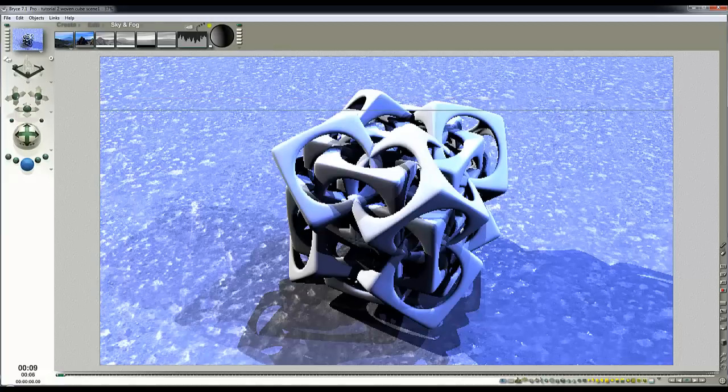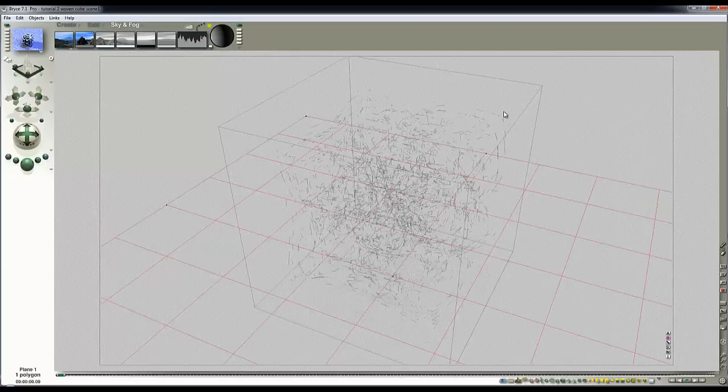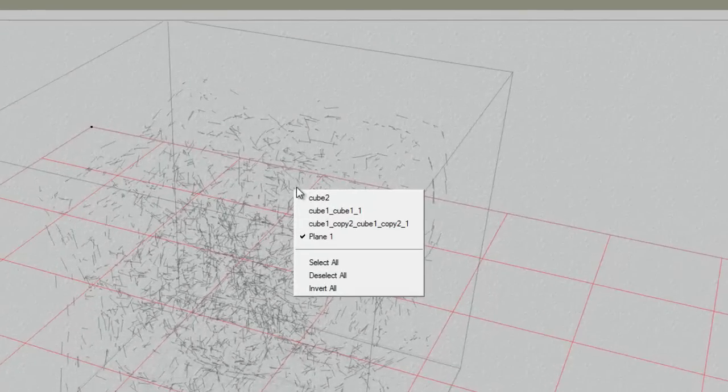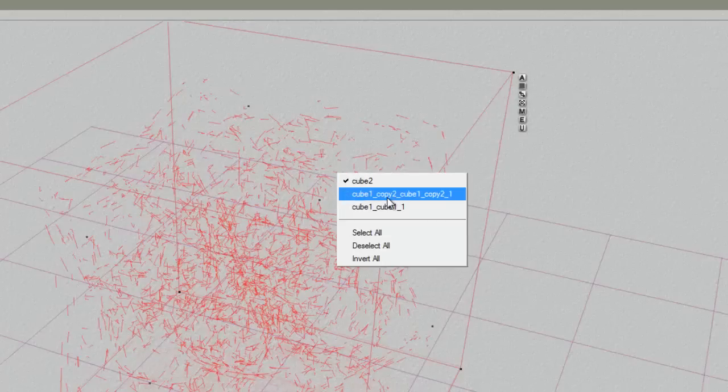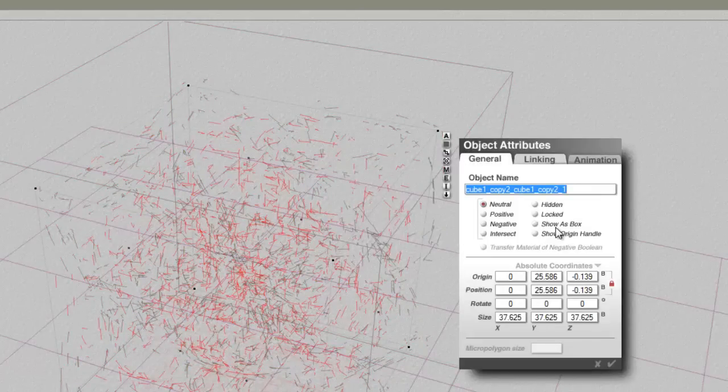So on these then we'll want just two different metals to show the difference between the two models. If I hold the control key down and left click where the cube is, you can see there's the entire cube model, which is the group here, and then right click again, there's the two components. To make life easier for yourself, it's a good idea to select the components. So that could be, and change the name, inner group, inner selection. It's not really a group, is it?